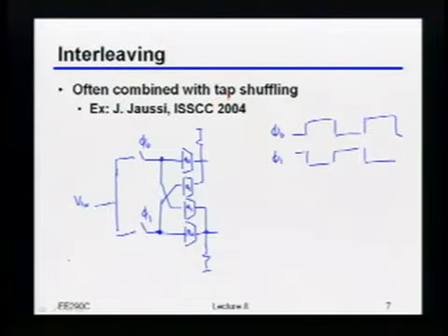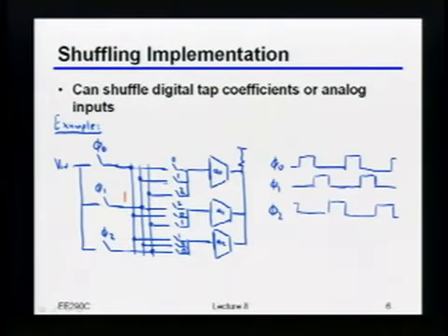And by the way, you can see I complained a lot about it, but for 2 taps, maybe even 3 taps, 4 taps, it's complicated, but it's not that bad, right? It's really only if you start talking about very complicated things, maybe 5, 10, 20 taps, that it starts getting painful because the noise just starts to accumulate, right? So, as I said, it's not particularly popular in high-speed links because in links, many times, if not directly, maybe indirectly, you can go back to your transmitter and say, okay, you should be doing the following FIR filter to operate on this particular channel.